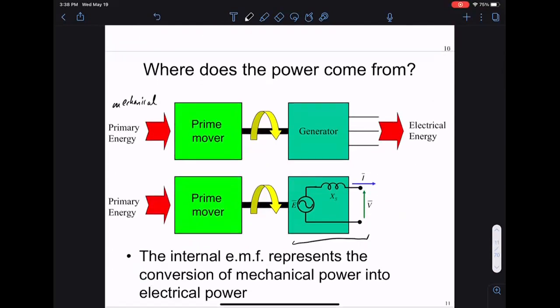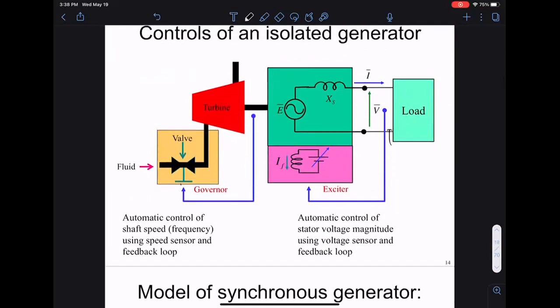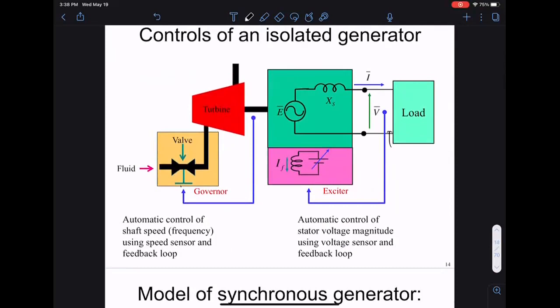All right. So if you look at these control loops, there's some interesting cybersecurity thing going on here, because I can easily make the whole thing unstable by hacking this. For example, I can reverse the sign of the feedback controller. So when the load demands less power, open up the valve, shoving more power, and then blow the generator up. Basically, that's one way to do it. And people have done this.